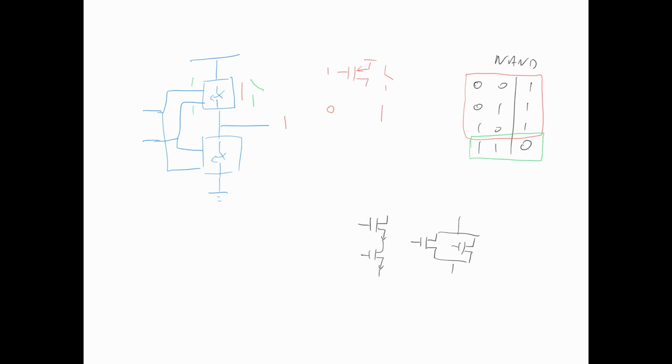Anyway, we're in the situation where we want this switch to be open if both inputs are a 1, and each individual switch is such that it will be open if a single input is 1. And remember, we can't achieve all possible combinations, but we know that we can make a NAND gate with p-channel FETs on the top, and so it will be possible to make this kind of a switch by combining p-channel FETs in either a series or a parallel fashion.